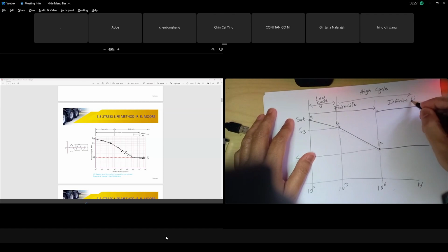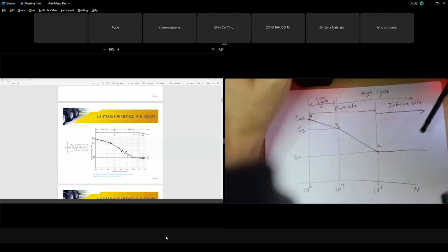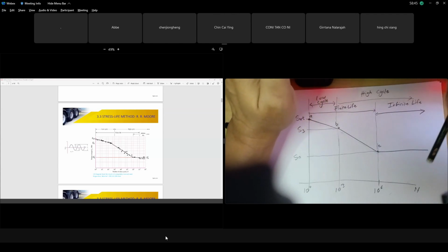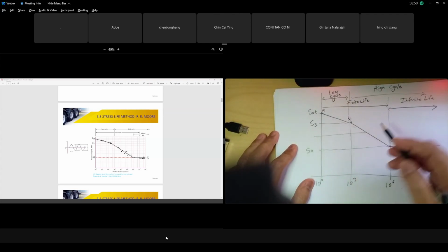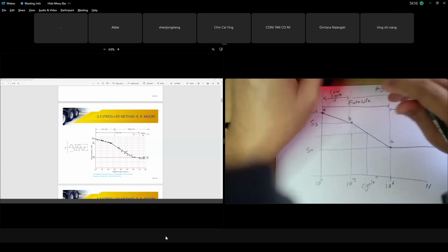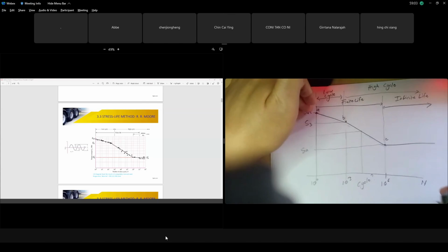Generally in fatigue analysis we go for infinite life. But sometimes, like I explained earlier, when your safety factor N, the endurance limit over your sigma E, is less than 1, meaning the stress applied on your specimen is greater than your Sn, you can predict at what cycle it will break based on this graph. We want to plot the log 10 graph.